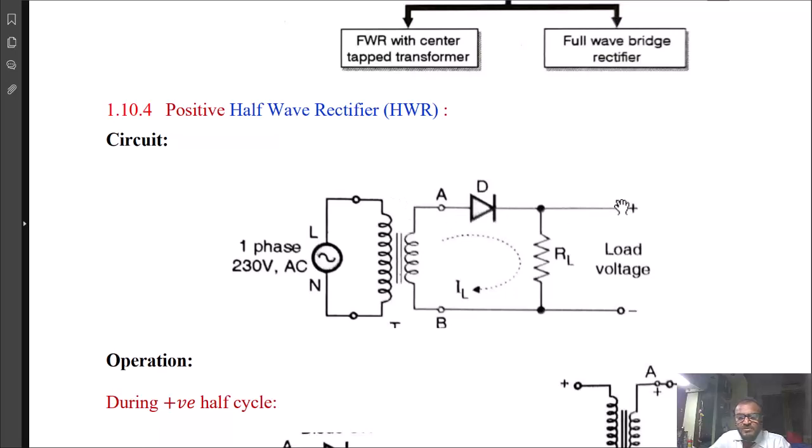Since we need a lower output voltage than the mains voltage, which in the Indian region is 230 volt AC RMS, 50 Hz, single phase, whereas the secondary voltage required is normally in the range of 5 volt to 15 volt, we need a step down transformer.